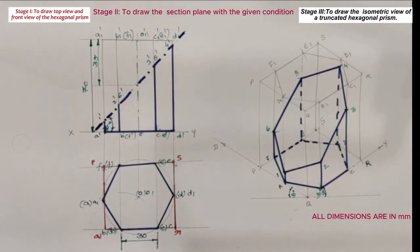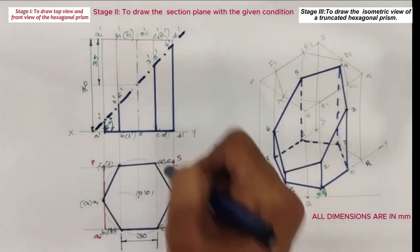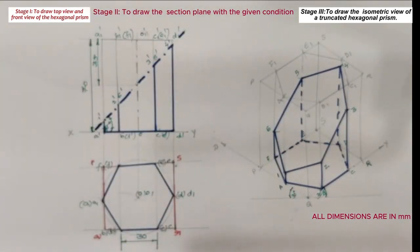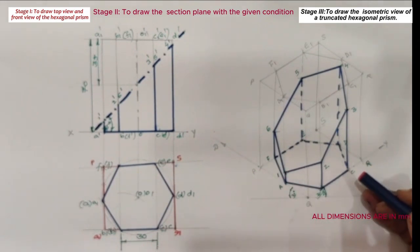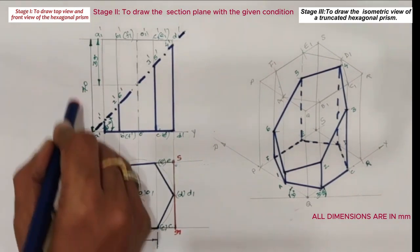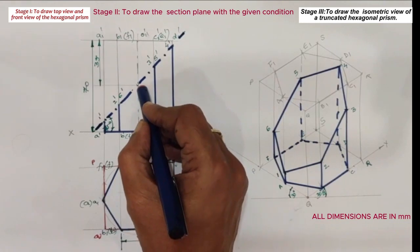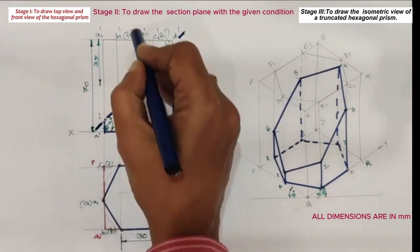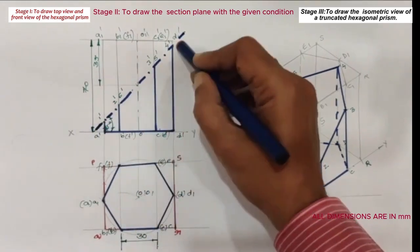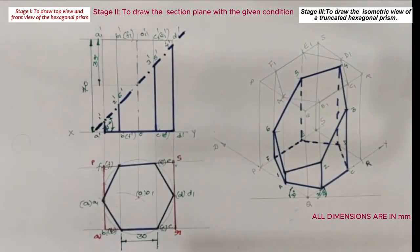Related to the pencil uses, the blue color lines are drawn with H pencil whereas remaining lines are drawn with 3H pencil. Blue color lines are with 100% darkness whereas remaining lines are with 25% darkness. Here base side length is 30 mm and axis height is 70 mm. Section plane is passing through the axis, say 35 mm from the bottom base or 35 mm from the top base, that is the section plane is bisecting the axis. All dimensions are in millimeters. That's about the solution for the given problem.